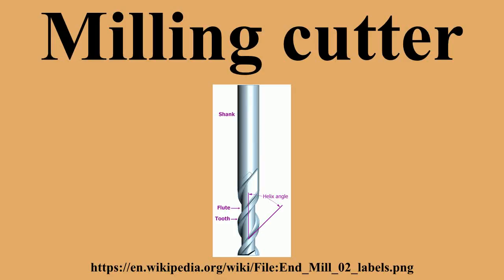They are the most common tool used in a vertical mill. Roughing end mill. Roughing end mills quickly remove large amounts of material. This kind of end mill utilizes a wavy tooth form cut on the periphery. These wavy teeth form many successive cutting edges, producing many small chips, resulting in a relatively rough surface finish. During cutting, multiple teeth are in contact with the workpiece, reducing chatter and vibration.